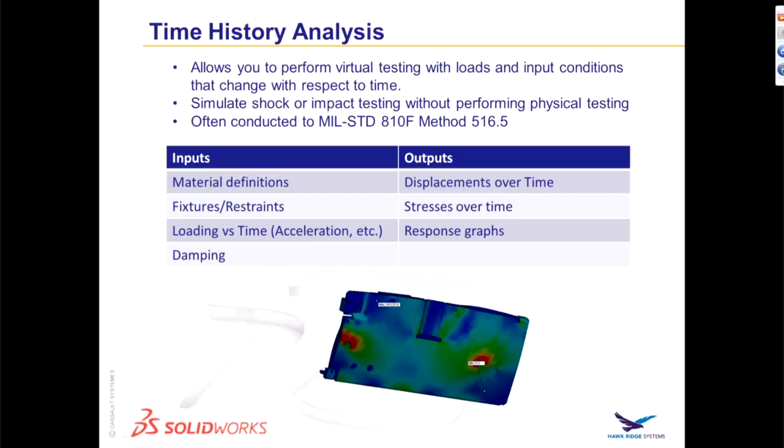You might remember that we were saying the force we had was applied slowly over about 1 second. If we wanted to simulate that that was a shock load, though, that happened maybe in 1/10 of a second, that nonlinear analysis, which was still a static analysis, would also not give us the correct answer. So the time history analysis would be required if we expected any kind of vibration effects from applying this load so quickly.